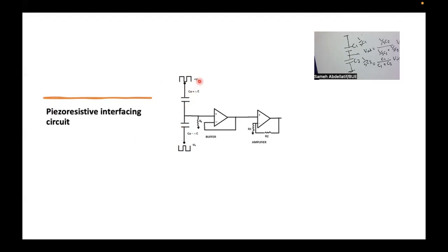A second important comment is that when you make this pulsive signal, that simply means you are forcing your capacitors into what we can call a charging and discharging cycle. When the voltage is high, your capacitors will charge. When the voltage is low, your capacitors will discharge. And here you should have a discharging element, otherwise you will not have this variation. Your voltage will be saturated, because if you don't have a discharging path, your voltage will be kept high all the time, since the capacitor couldn't find an element to discharge in. That's why we add this resistance. Its job is simply to be used as a discharging element. When the voltage tends to low, the capacitors will discharge in this resistance, and then this voltage will drop again to low and so on.